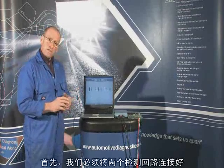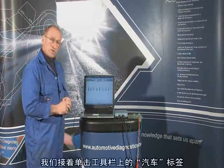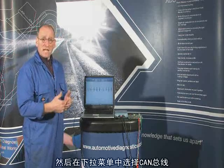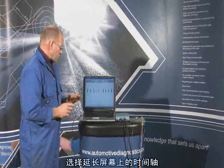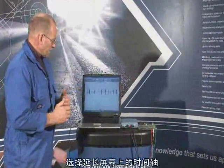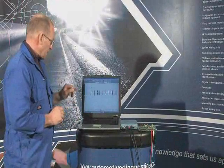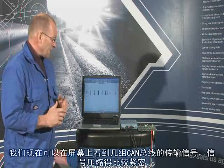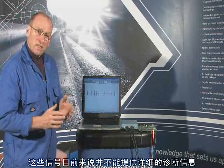I've initially set the tool up. There's a couple of ways you can go into CAN. You can click on the automotive icon in the toolbox and pull down the menu and select CAN. There are three options within that program. I've chosen to put up a screen time of 50 milliseconds per division. And what you can see now is several packages of CAN data across the screen. It's highly compressed and diagnostically has no detailed meaning.